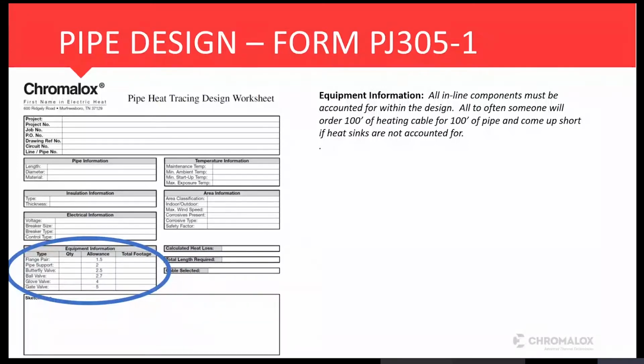Always ask, are your pipe supports, how many are there? They could say, I don't know, and say, well, that's fine. We'll space them every 15 feet, every 20 feet. Are your pipe supports insulated? Are they non-insulated? These are all questions that need to be asked.